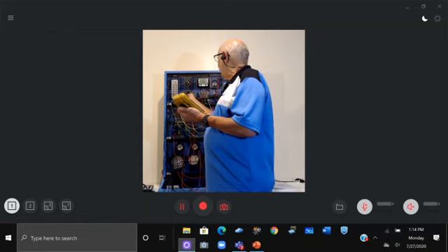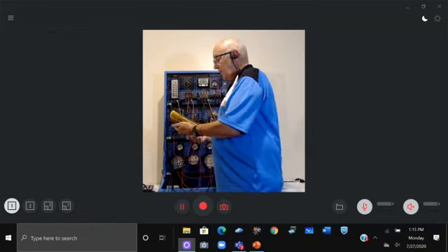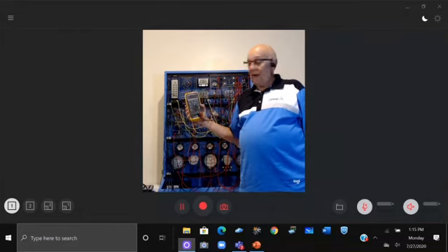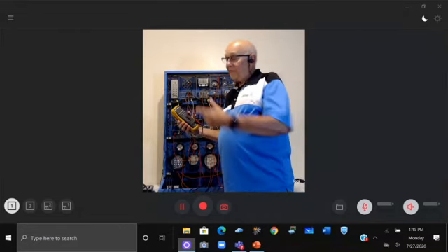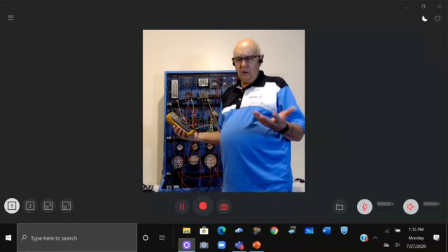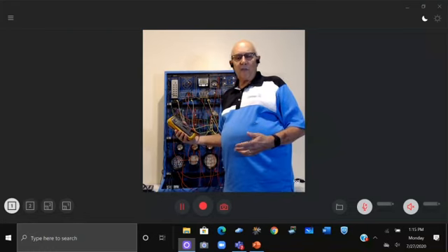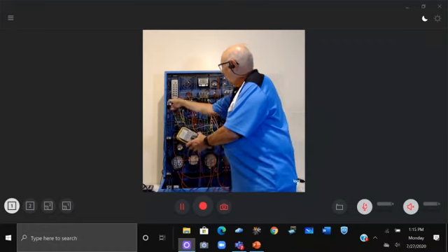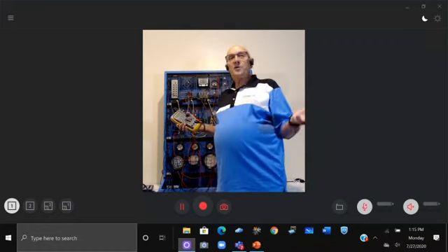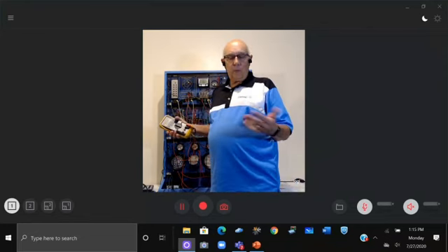And by the way, you don't have to worry about polarity or anything else. Let's see. No, can't read it. Anyway, it says 59.4 ohms. Al, you said there are 120 ohm resistors. Yeah, but how many of them are there? 1, 2. They are wired across, which is another way of saying they're in parallel.